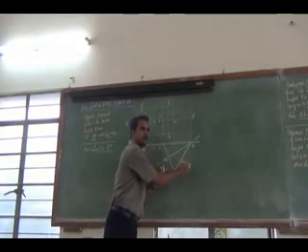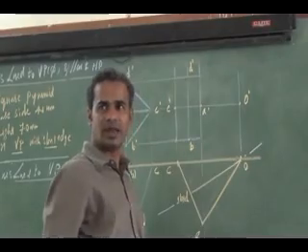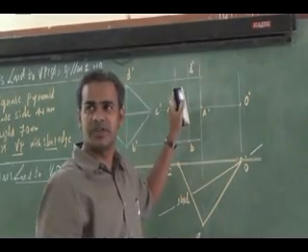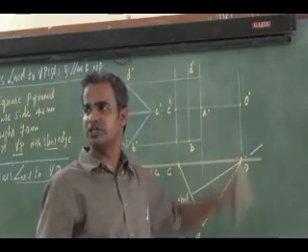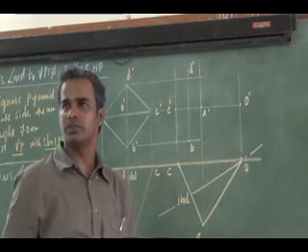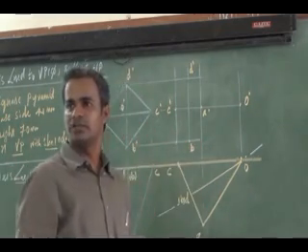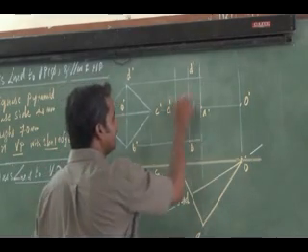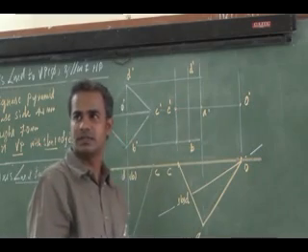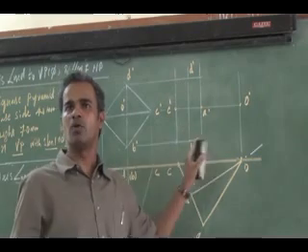The final top view, and from the final top view I have drawn vertical projectors from all the corners, and from the previous front view I have drawn horizontal projectors from all the corners. I have got the intersection points, that is the final front view points. Then, as per the note, you have to show the boundary first of all.